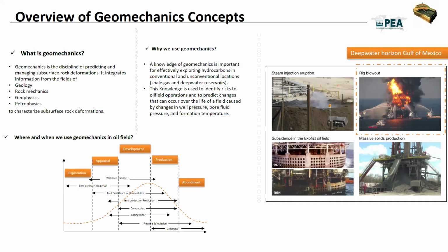As you know, the Deepwater Horizon, in fact, was a problem of wellbore stability and well integrity due to bad estimation of the pore pressure, or some people said non-estimation of the pore pressure at all. The reservoir was an overpressured reservoir, meaning HPHT, and began to deliver a high pressure, and everyone knows the rest of this drama.